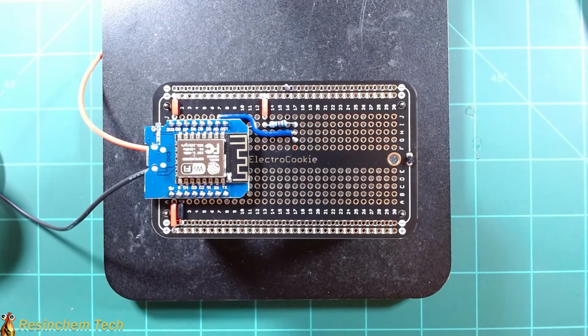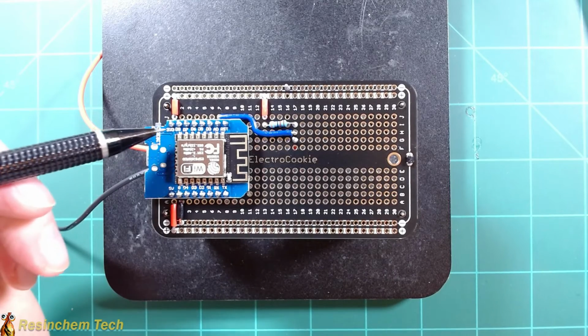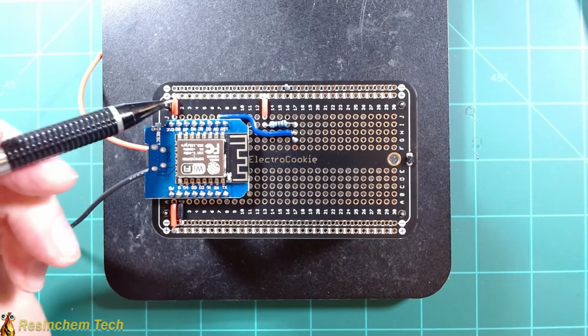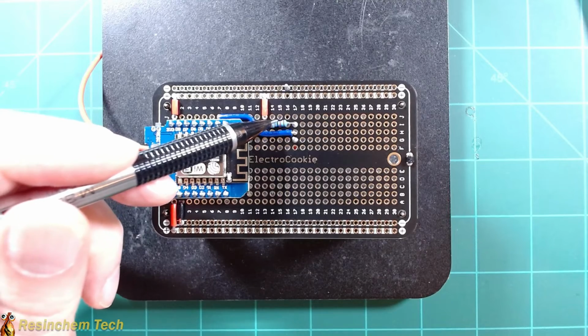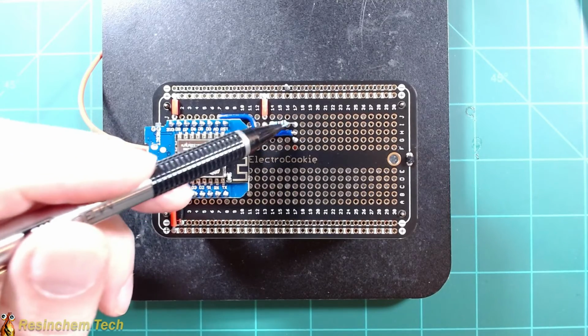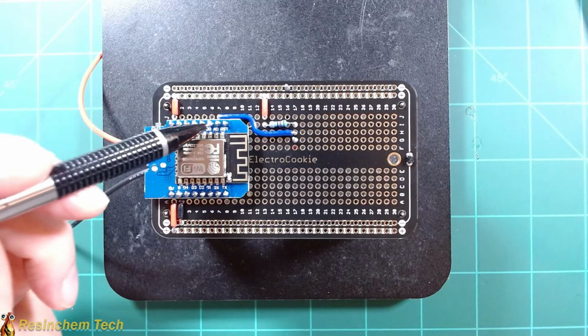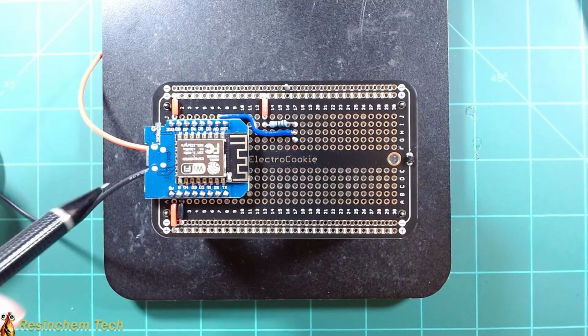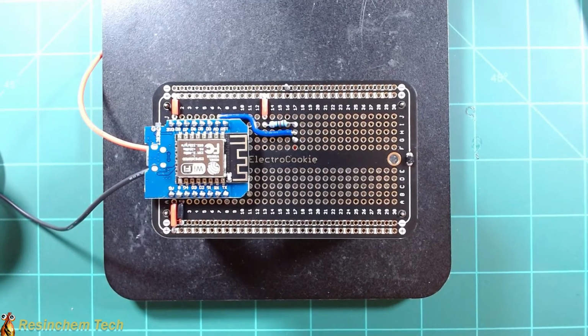This is the final soldered version, and it's pretty much exactly like it was on the breadboard. See, we're coming off our 3.3 volts from our D1 Mini to feed one side of a resistor, creating a voltage divider here that we're going to feed into our analog pin, and we've got our two leads that are going to go out to our force-sensitive resistor strip.